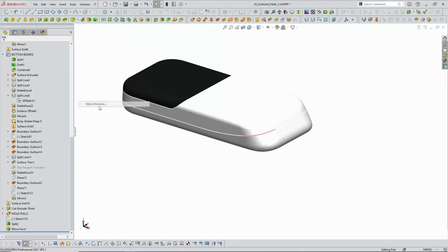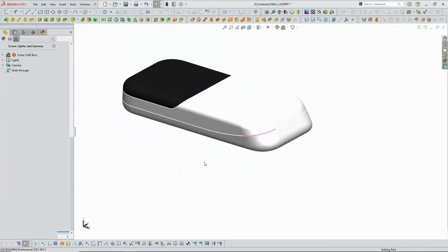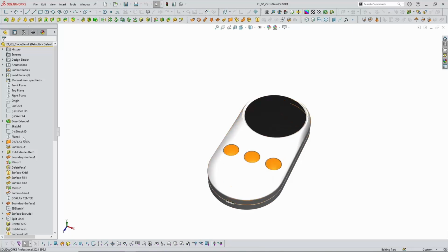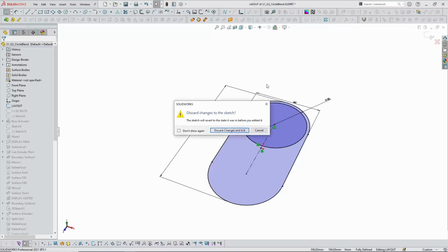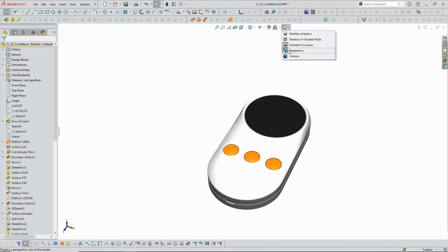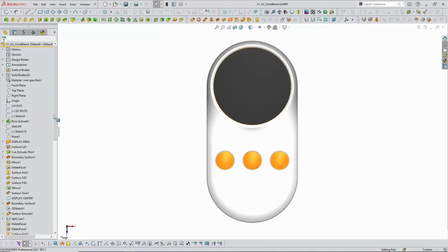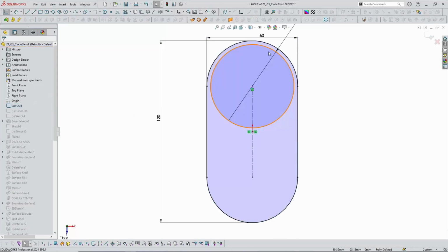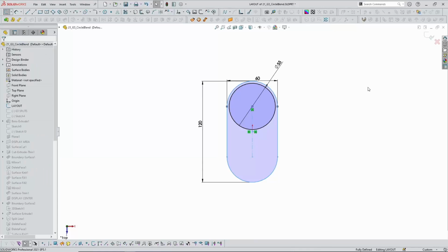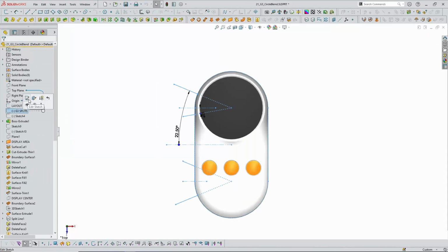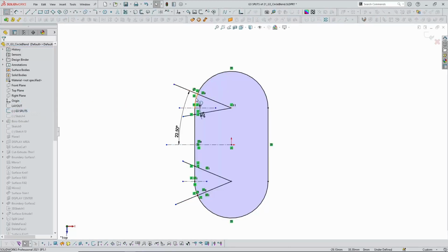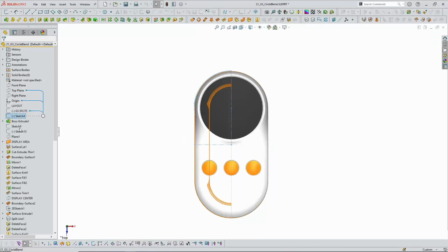So opening up this example, the way I did go about creating this is this initial layout. We'll turn off perspective. These are my arcs. I'm doing this at each level, so I'm not trying to do this all in the same sketch, so I convert into my next sketch to be able to define these splits. And I'm also not putting the G3 in this one. I found it just works a little bit better if we split everything out.